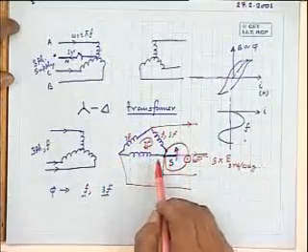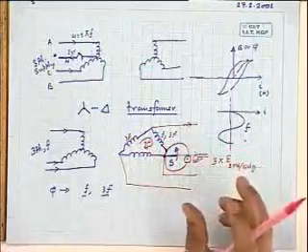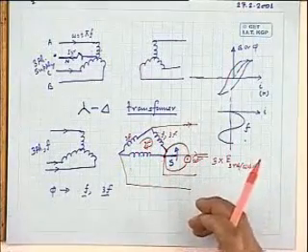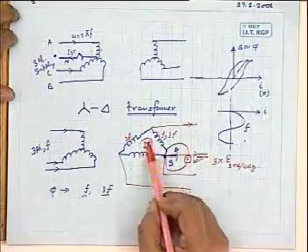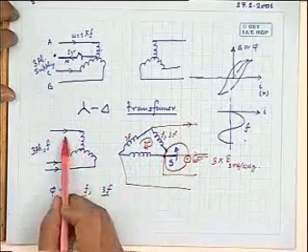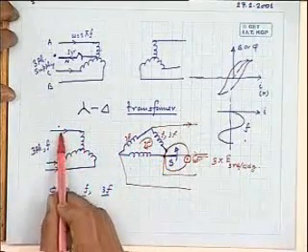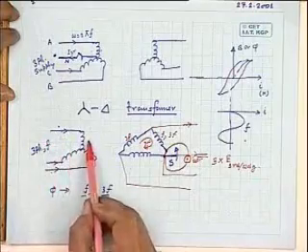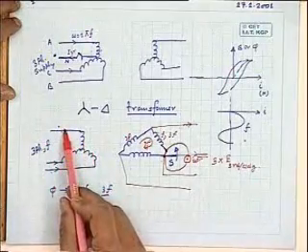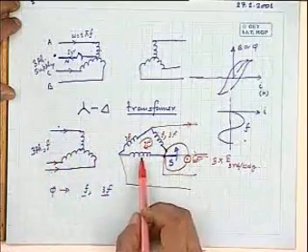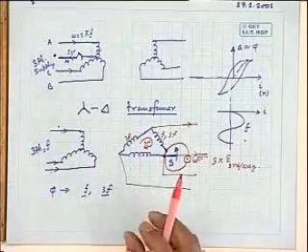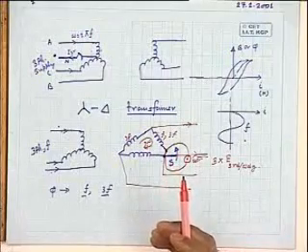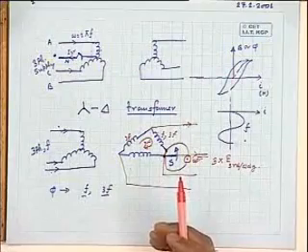Now what happens is this, in this particular type of connection where delta connection is present, the transformer can produce its own third harmonic current requirement. See, this current, third harmonic current, will have no component reflected on the primary side, because here no third harmonic current can be present on this line, because neutral I have not connected. Therefore, what happens is this: the magnetizing current will now consist of this fundamental frequency, whatever is drawn from this supply, and the much needed third harmonic current the transformer develops by itself, and trying to make the flux more sinusoidal.